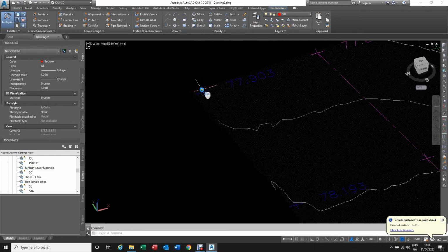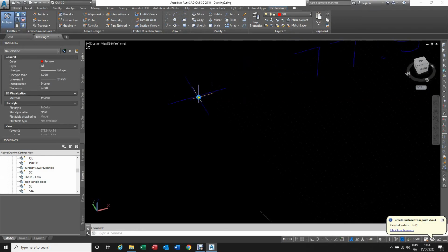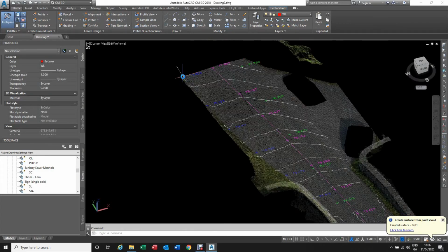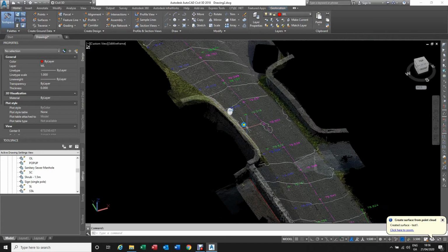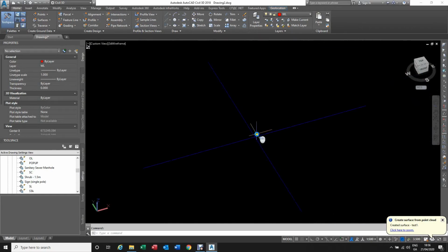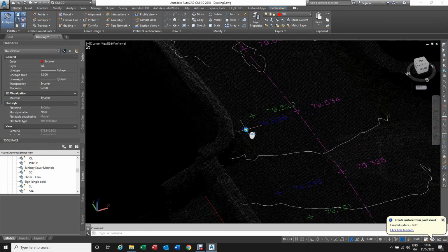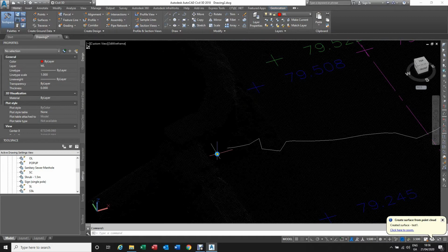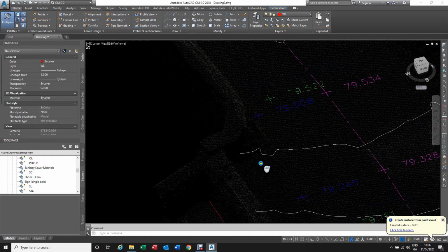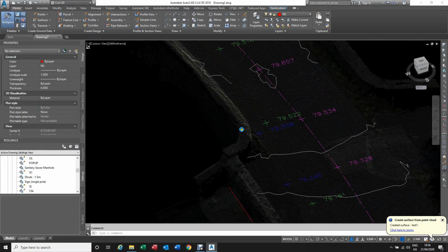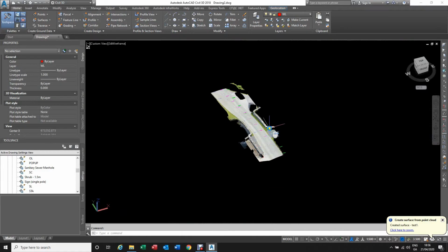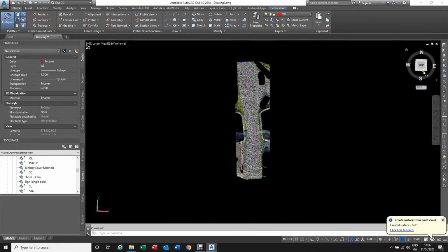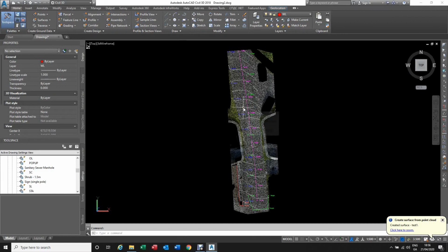One directly attached to one point on the point cloud, and there were points made, not on the point, you see there's no point here, but on the surface. Sometimes when you have no dense area like here, you already have a thin surface under, then it's better to use these kind of points. And once you have the points done, you can just switch off F4, switch on F3 for snap-on.